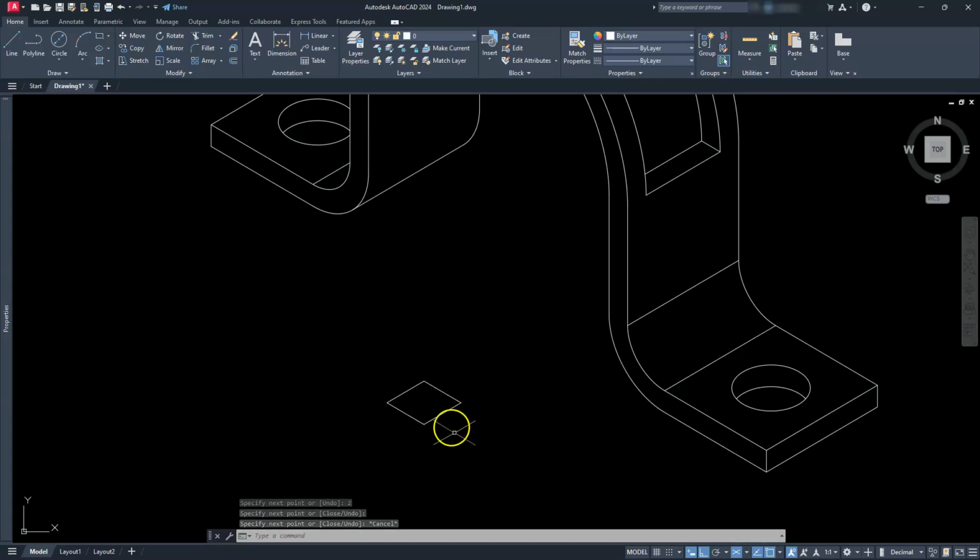All right, so what I have here is the center location of what I need, right? And it might be a little more beneficial in this case to go ahead and draw my ISO circles along this view. So I'm going to go to ellipse, I enter, and that stands for my ISO circle. I'm going to click here, and then go to here, right? So I'm going to place this first ISO circle, which is going to be located here. So I'm going to select this circle. I'll go to move from this endpoint to that endpoint.